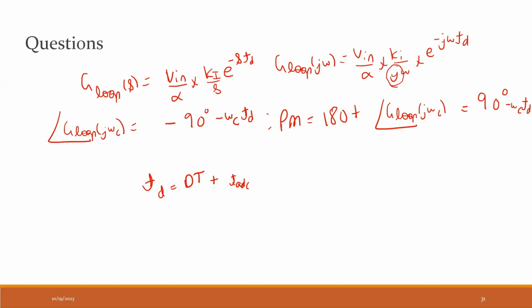See, when you give a disturbance, how your system will respond is determined by the phase margin. Assume your phase margin is low and some disturbance occurs. Assume this is your output step: your output current has increased, a step up transient. Your output voltage will reduce and will come back. This is what we prefer it to be.